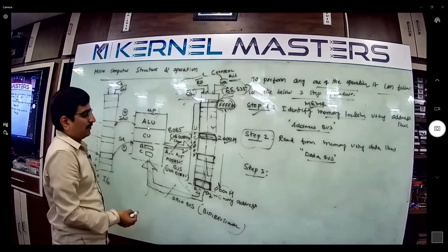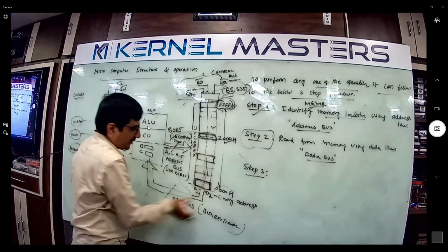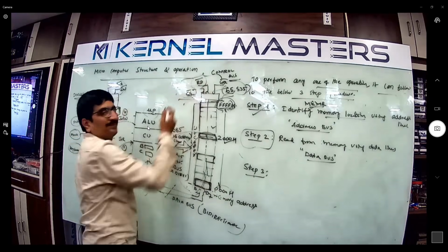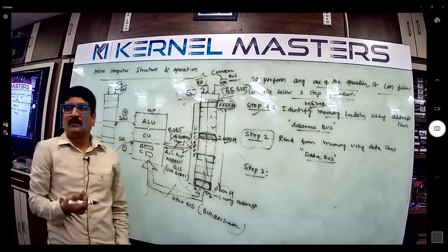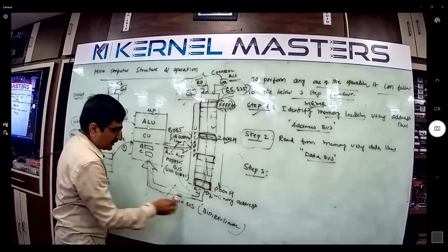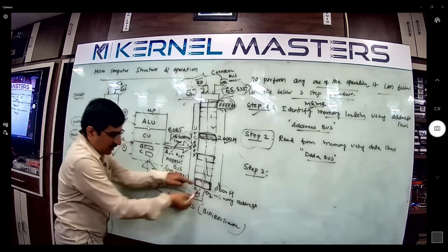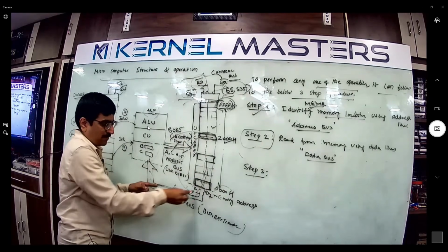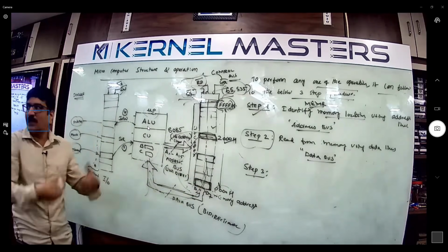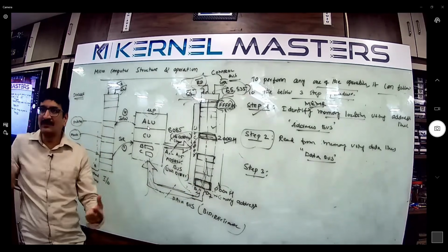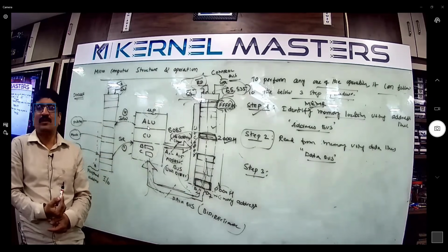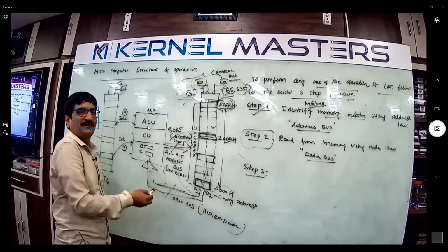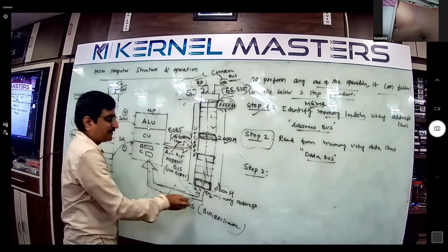Whenever you perform a read operation, the read bar signal should be low. The same line can be used for reading and also for writing. That's why, since the bus is bidirectional, you need a control line to say when you want to perform read or write. That's why there is a tri-state buffer. The bus is the same, but sometimes you want reading and sometimes writing.